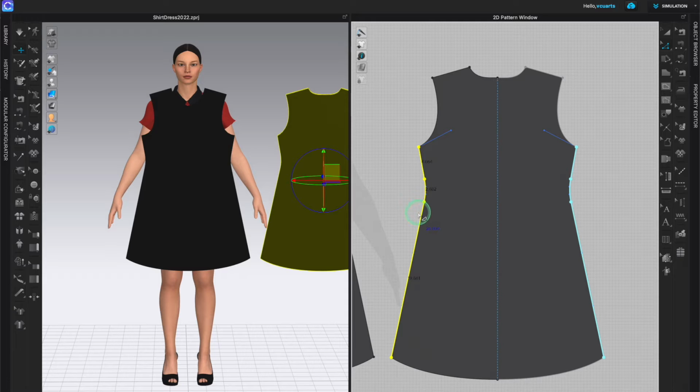So this is helpful because when you need to remember in CLO, unless you surround all of the piece, you're not going to have a full selection. So this is why, by dragging this entire marquee box around this side, that it allows me to just select this full outseam from segment point to segment point down here without selecting this armhole and without selecting this, because the marquee box didn't include the entire section of that armhole or hem.